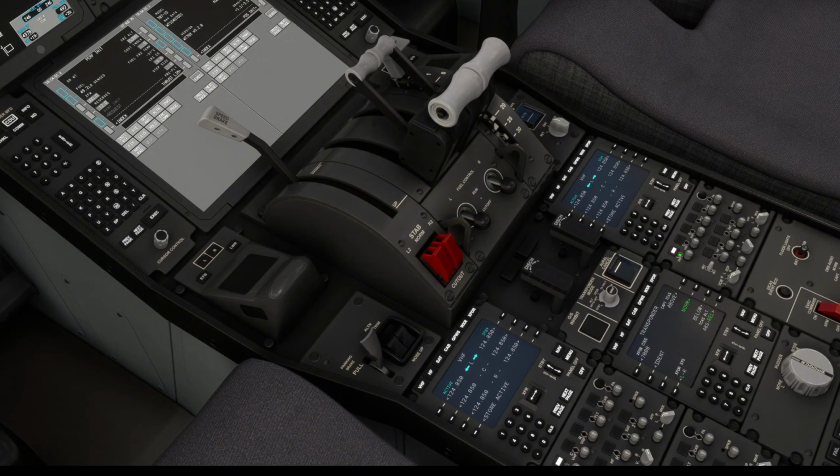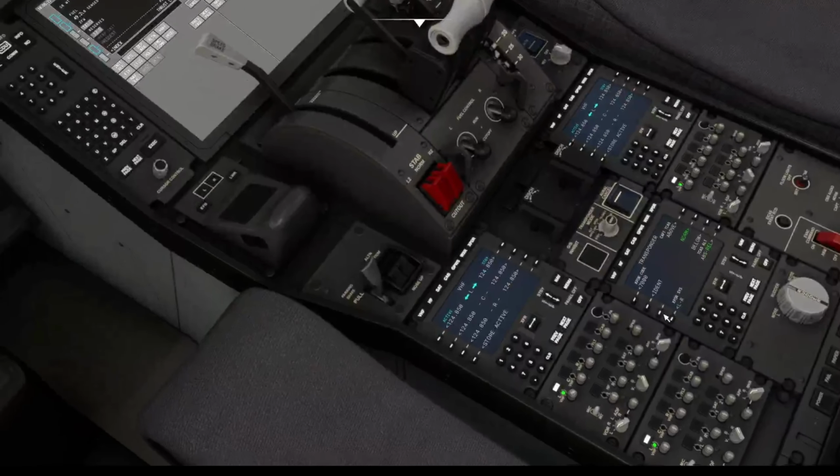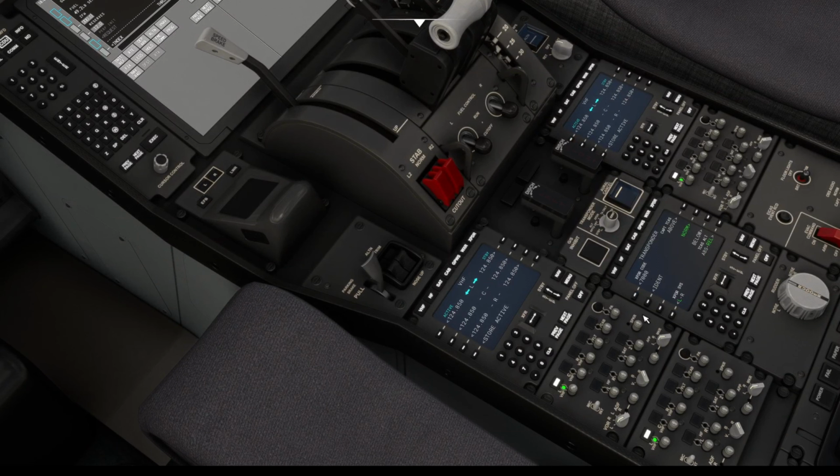And I think that if you have it on above, the TCAS shows you all the airplanes which are 9,900 feet or something like that above your airplane and 2,700 feet below. And if you flip it to below when you are in cruise, the main focus of the TCAS display is to show you all the airplanes which are like 9,900 feet below you and only 2,700 feet above. And normal, I think, is like 2,700 up and down, something like that. So yeah, squawk code is also received by clearance usually.